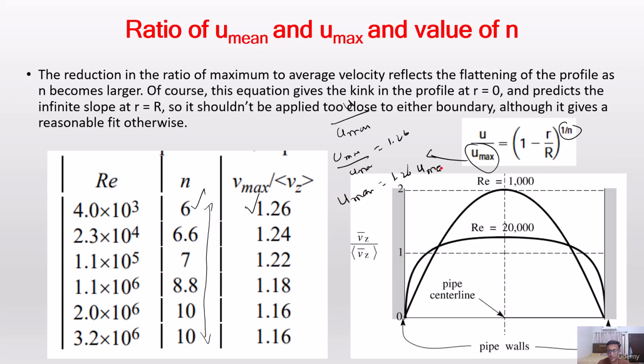So why are we doing this? Because we know the U mean, that is the inlet velocity, but we don't have an idea about the U maximum. So in the formula, you can replace it when you want to plot that in Excel. You can replace this with the Reynolds number of 4000. Then you can put this formula there, and U mean is the velocity at the inlet.